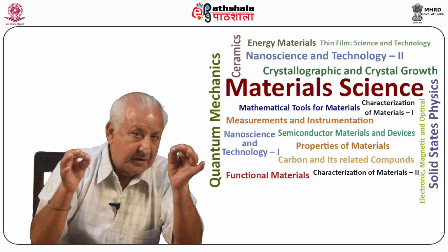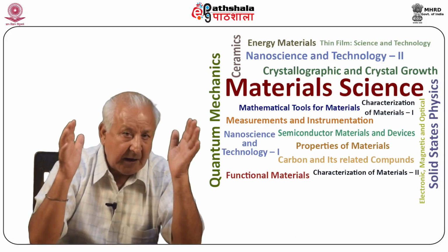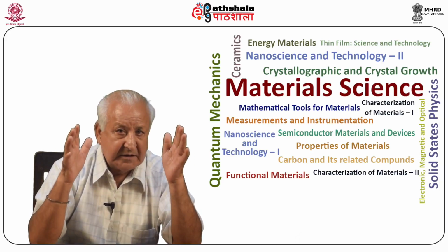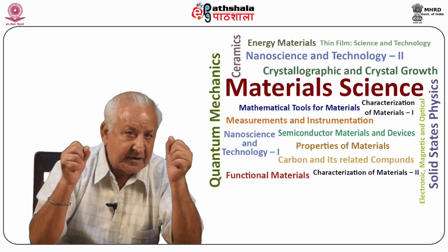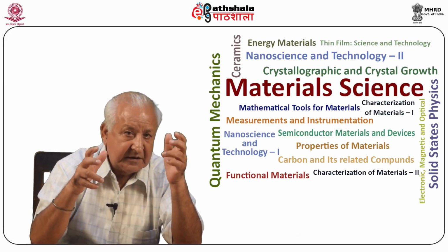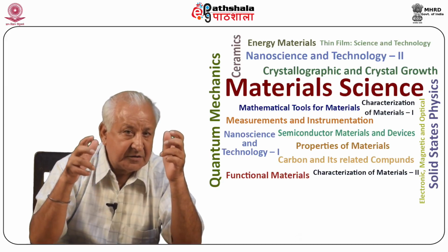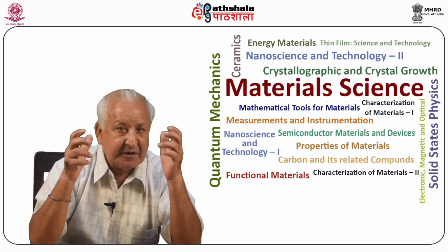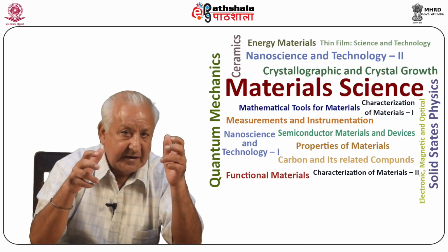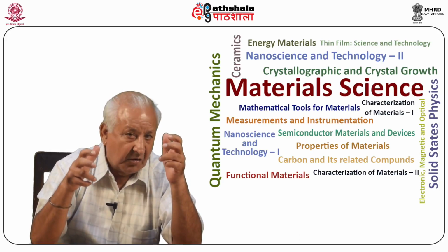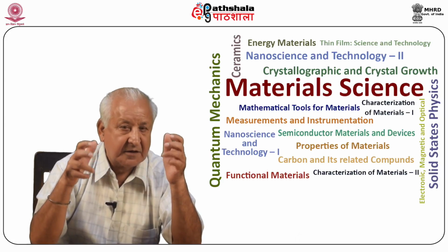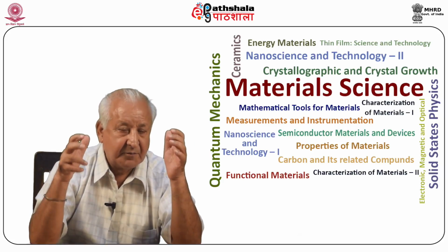There is also a problem which is associated with the encapsulant, and this is contamination. Small particles in the melt have a tendency to get trapped within the encapsulating layer, which impairs visibility. Conversely, some of the encapsulant may get dissolved into the melt and act as an impurity ion. In spite of these problems, gallium phosphide can be grown in weight ranges of 2 to 5 kg by this technique and has acquired the status of a commercial production process.